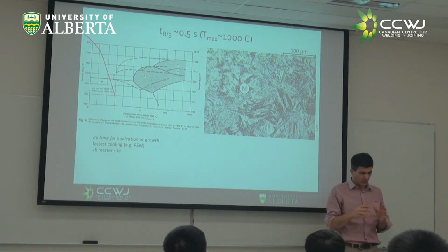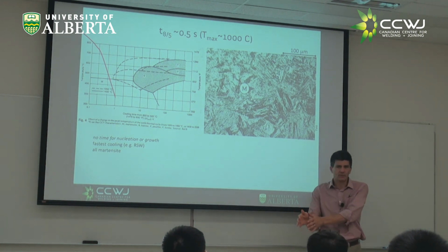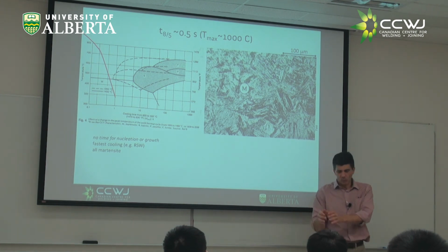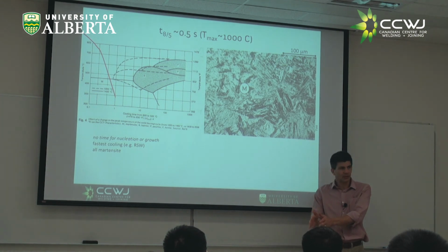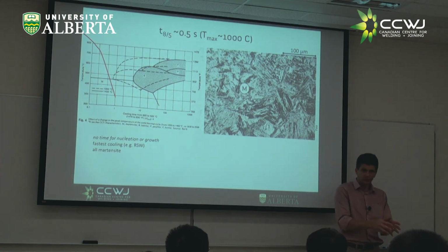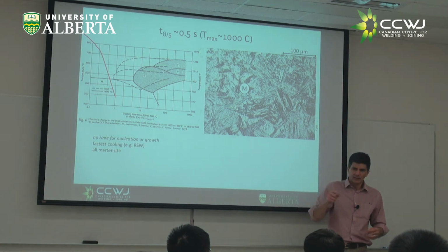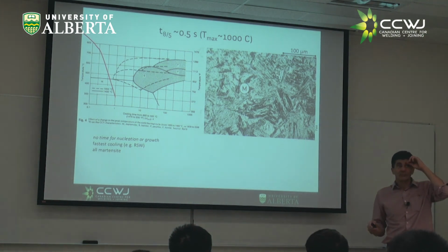And that relates to welding with submerged arc welding, that is a very slow cooling rate, or electroslag, or laser welding, a very fast cooling rate. But in a laser weld, pretty much all places in the weld have the same cooling rate. In submerged arc welding, pretty much all places in the weld have the same cooling rate. Okay? So the effect of cooling rate is more related to the process than to the internal metallurgy. All right,